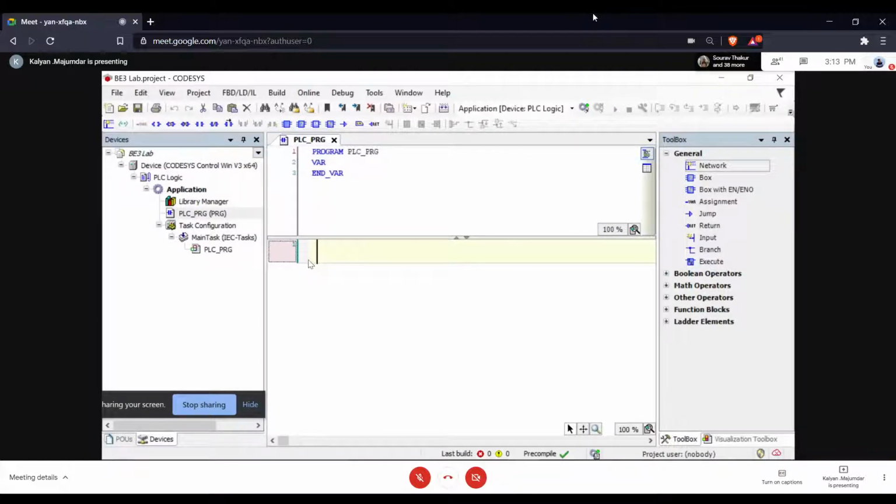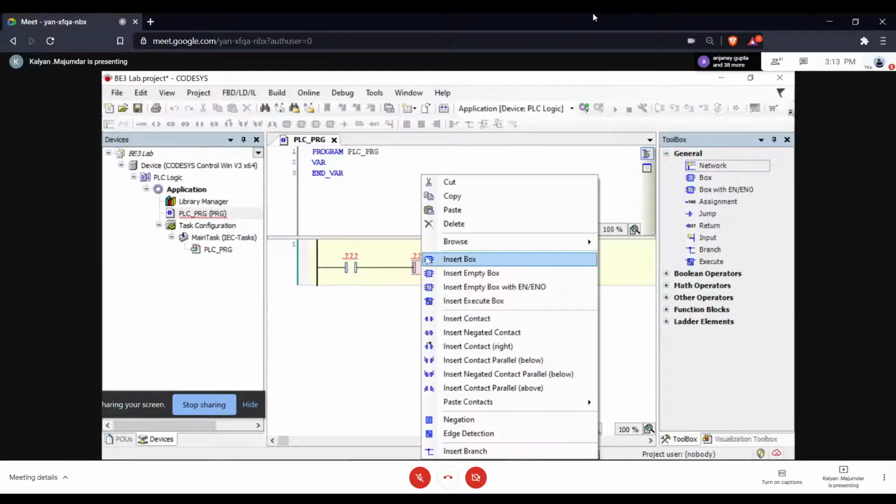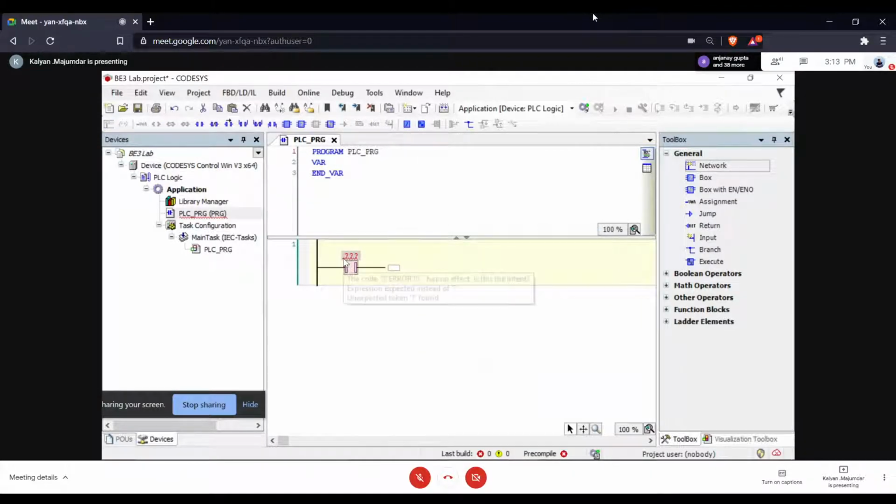Let's start off with the program development. The program development was, see, this is a normally open contact. You can select it from here, or you can also select it from function blocks, ladder elements here. But instead of going here, I think this is an easier option. This is normally open contact. I need only one of them. This is representing your start contact.